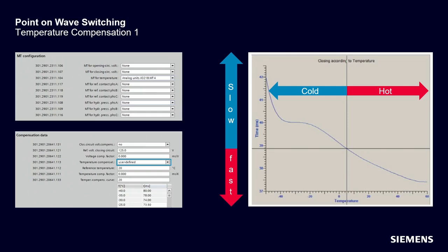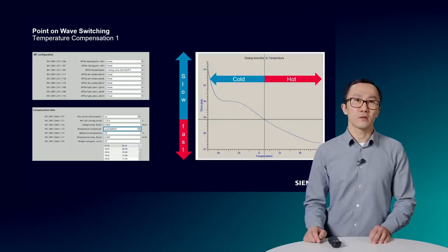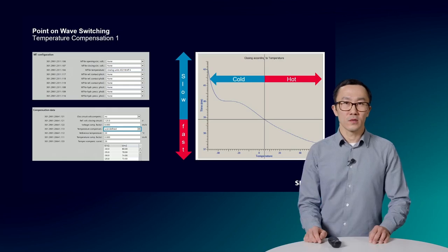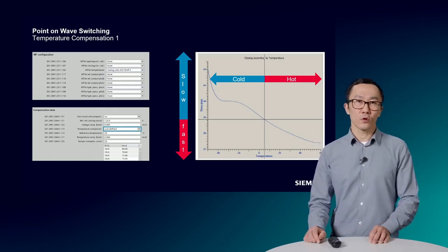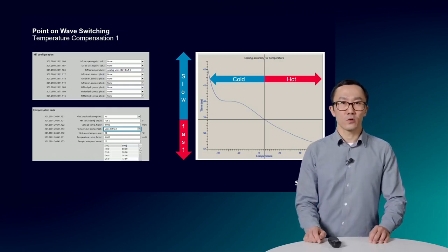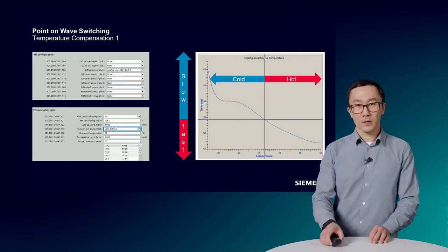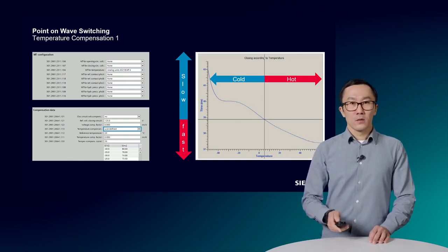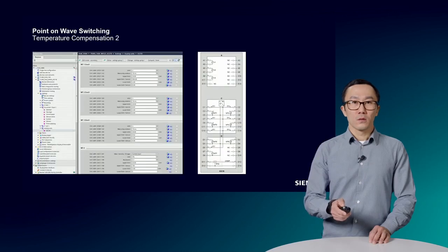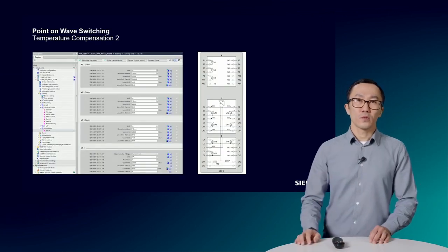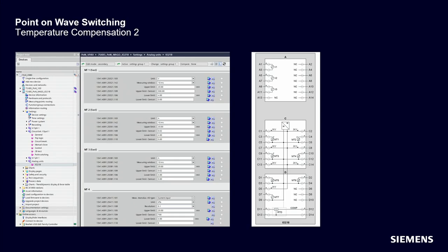Important to mention is that you need to define the reference voltage for temperature compensation. This can be entered in the parameter number 121. The temperature is set assuming nominal 100% control voltage over the defined temperature range. So you need also parameter transducer input for temperature compensation in the function group analog units. You can define upper and lower limits, also limit for the sensor itself, unit and measuring window.